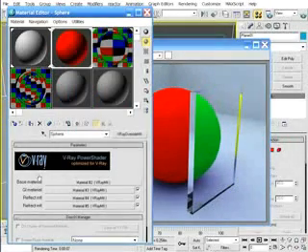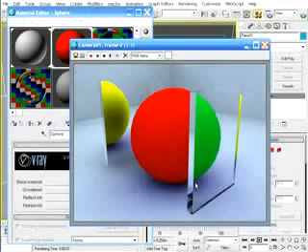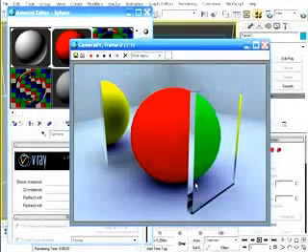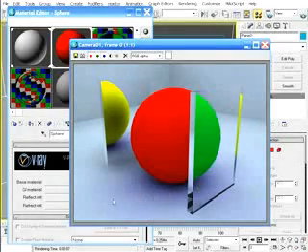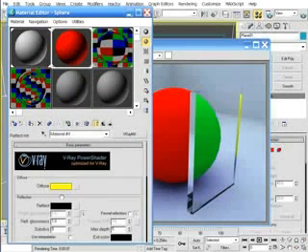If you load a map, the colors in the map will be reflected instead of the base material also. This is a wonderful way to control the amount of color and bounce light in the scene, and in a moment we'll look at a more practical application of this particular procedure. The different reflection and refraction materials are pretty straightforward.